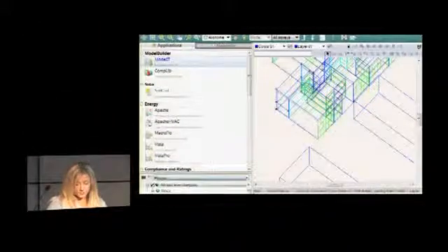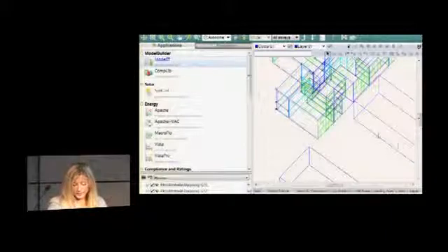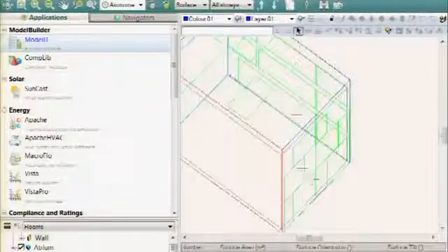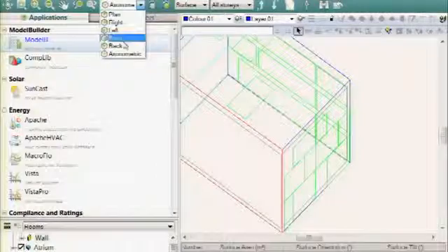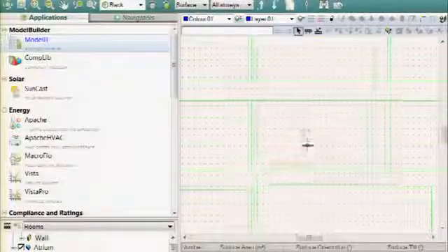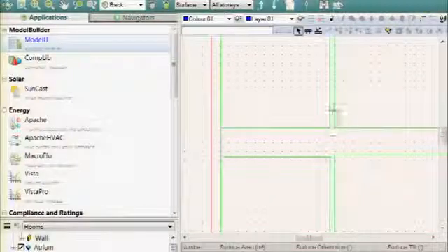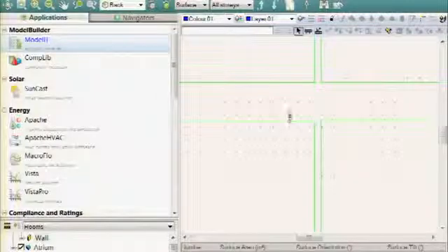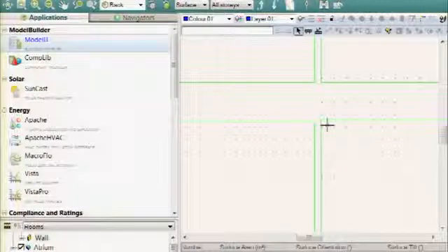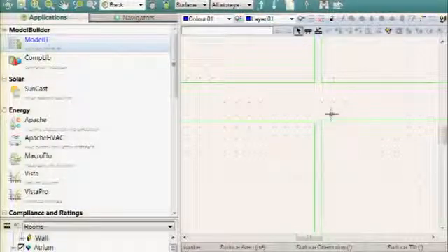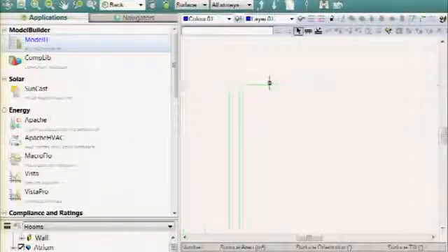So when you bring it through, you're going to see, let's see, it comes through a little odd sometimes. So this right here is an example of layering of windows. So I'm just going to show you some things that I've seen. Often you'll get windows that come through with this issue where they may not completely align. And this is from not having a single element as a window. So here you can see that these two are not aligning. So this person had done a bunch of individual windows and placed them next to each other.